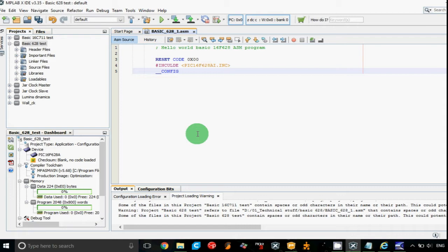Maybe you're using PonyProg or some other ICProg or something like this programs. I'm just gonna program it using the MPLAB environment, as you will see. But it's always helpful to have these declared right here. So the first one I'm going to write refers to the type of oscillator, and you declare it like this.